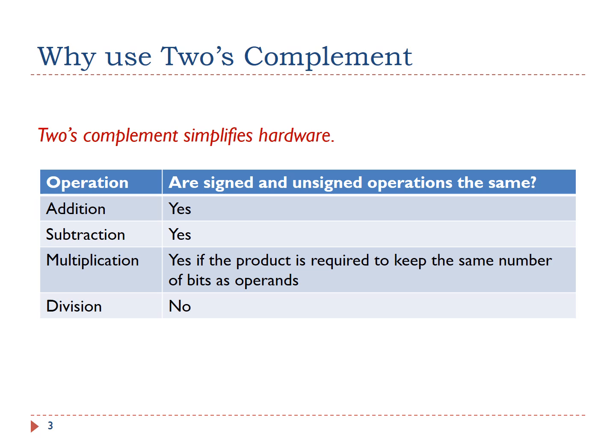Why do we use 2's complement? One of the advantages is that 2's complement can simplify the hardware implementation of arithmetic functions. For addition or subtraction in 2's complement, the hardware can ignore the sign of operands if signed integers are represented.